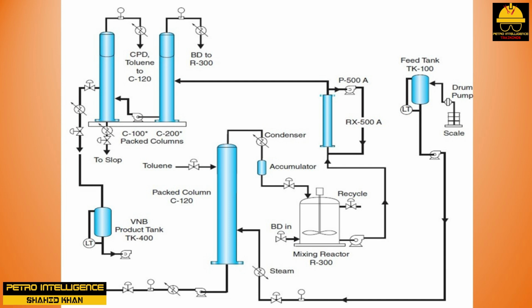The reactor resembles a shell and tube heat exchanger with 3 large tubes. The outer jacket is filled with hot oil that maintains a specific set point. A large centrifugal pump circulates the feed through the reactor as the synthesis reaction occurs. The reactor is mounted vertically, and flow moves clockwise through the tubes.